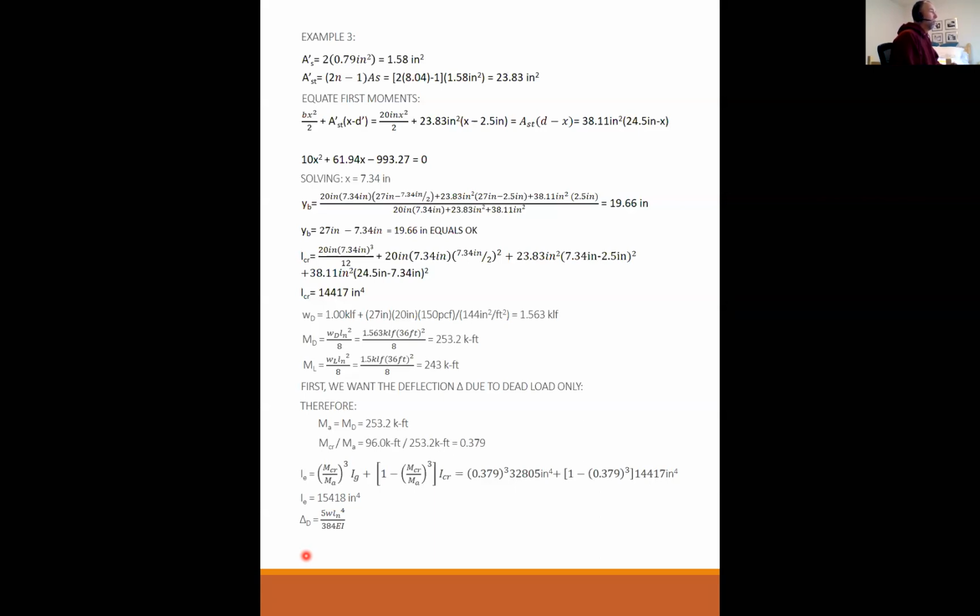Live loads are almost always given in pounds per square foot. Your house is 40 pounds a square foot. Parking garage is 40 pounds a square foot. Egress is 100 pounds a square foot. Light storage is 125. Heavy storage is 250. Most of your given loads are pounds per square foot. So anytime you're designing an area, you use pounds per square foot.